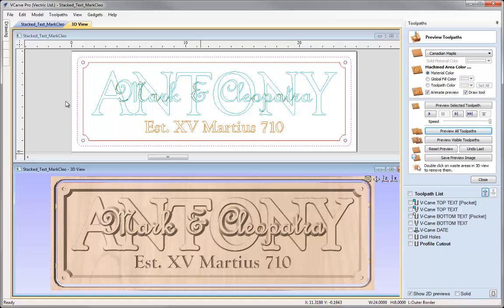Eventually, once we got a part that we liked the look of, we were able to save that both as something we could cut at the state where it was saying Romeo and Juliet, but also then to clean that up a bit and save that as a template file. We went out into Windows, we set that template file to be read-only to ensure that if we use it in future we can't accidentally overwrite it, and like you saw me do here then, we can use that template to open, create a separate version of it, and very quickly and easily edit the data that's in it and use the same set of toolpaths again and recalculate them very quickly based on having used that vector selector when we did our toolpath setup. And that concludes this example.